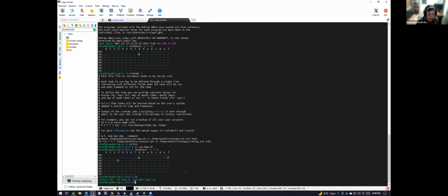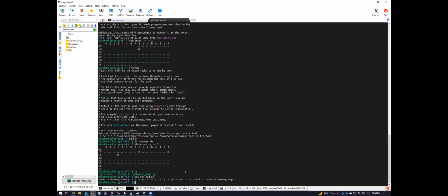Do you think the local board failed? Yeah, and that's what I think has happened on mine too. Here's how I have run mag configured. So -M is the remote magnetometer, so that's 23. That's correct. See, I had -R, I guess it's the remote temperature sensor. Yeah, you have it as 1F. Yeah, that's what I had it as. So now -L, is that supposed to be the local temperature?